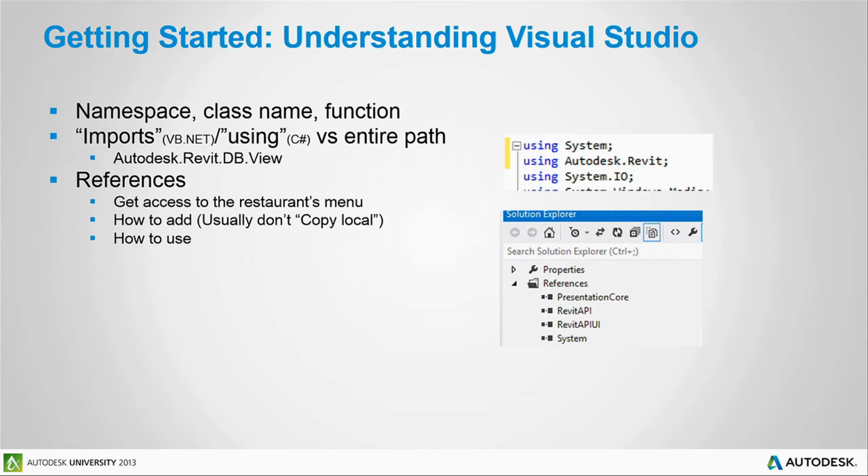On to the second point: instead of having to type that out every single time, you can create shortcuts at the top of your code. When you first start looking at these example codes, you'll notice at the top, and I'm looking at the top screenshot here, most of the code, and that's C#, but if it's VB.NET it would be Imports, you're importing these shortcuts. Basically, that means that every time I say MessageBox.Show, it knows to look in those locations first. And if it can't find it in those locations, then it gives you an error. The important thing I want to mention is that when you go online, to blogs, to different places, a lot of times you'll get sample code. And the sample code a lot of times won't include the stuff at the top.